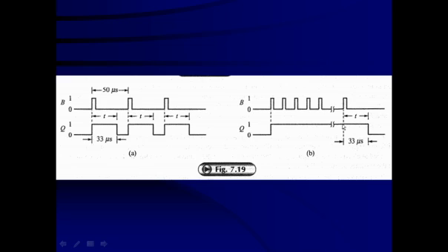When the positive transition of the last trigger pulse is there, it will be re-triggered again and the timing cycle is going to start from here, because thereafter there are no trigger pulses. So after 33 microseconds, automatically it will time out and go low. And this way, the pulse duration can be modified here.